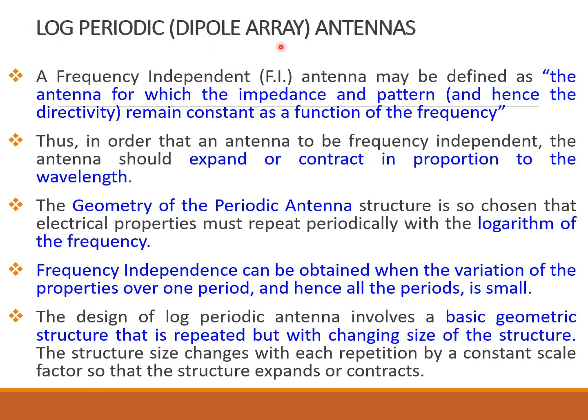Log periodic antenna is an example of frequency independent antenna. As I told you in the previous slide, impedance and pattern remain constant as a function of frequency. And one more point is that frequency independent antennas expand or contract in proportion to the wavelength.